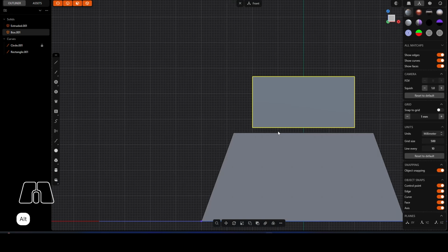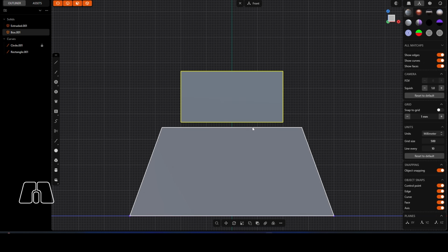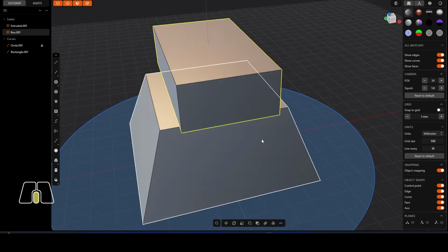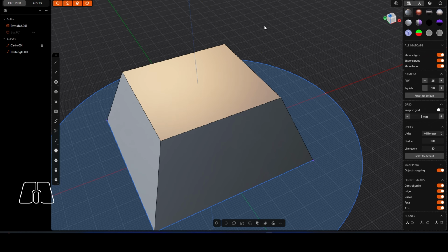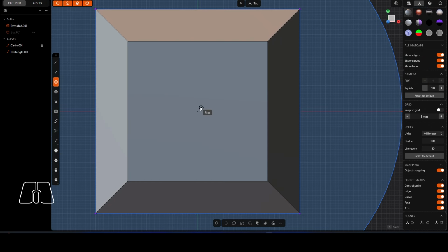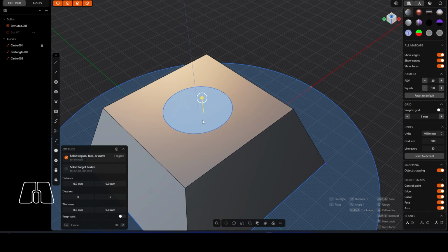So we can move that up, and then what we can do now is we can create a sort of pivot joint or a bit where this slots in. So if you're thinking about modular design, think about functionality, it's a good place to have maybe a pivot for this. So if we just hide our piece here and we come to the top and we use this, we can set this to be whatever base size we want. So again, maybe it's going to be fitting of some of the bases that you're using. So typically, you get 28 mil bases. Again, correct me if wrong, if you've got better base sizes for this stuff as well, put them in the comments, because obviously other people will need to learn, I need to learn as well.